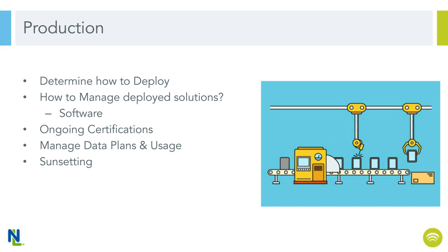Software, you almost have to use firmware updates over the air. If you don't think you need that capability, then you probably do. I don't think I've run into an IoT system yet where it wasn't important to be able to upgrade the software so you can add new features, capabilities, capacities to end devices over time. So you need to understand how you're going to do that and make sure it's rock solid.